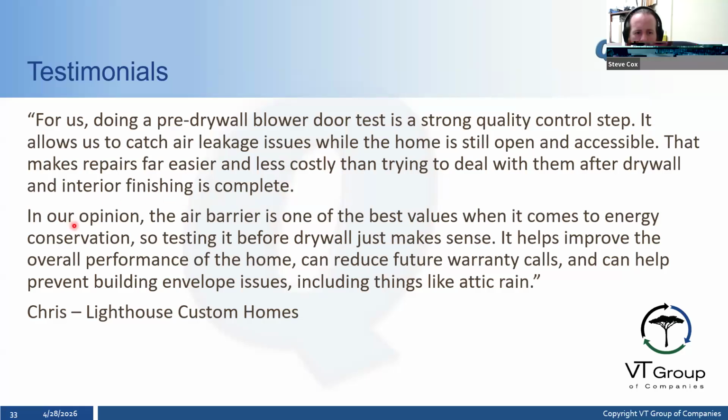In Chris's opinion, the air barrier is one of the best values when it comes to energy conservation. So testing it before the drywall just makes sense. It helps improve the overall performance of the home, can reduce future warranty calls, and helps prevent building envelope issues, including things like attic rain. We didn't talk on that, but that's something that we do a lot of testing and diagnosing on, if there's attic rain.